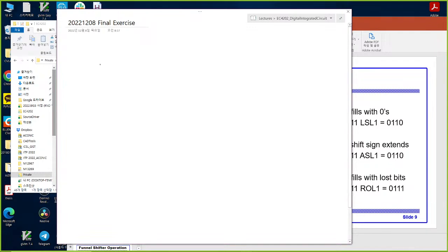For example, the 4-bit number is minus 8 in decimal. How do we convert that 4-bit to 5-bit? How do you represent minus 8 in 5-bit? Didn't you learn the 2's complement concept and how to use it in digital design?